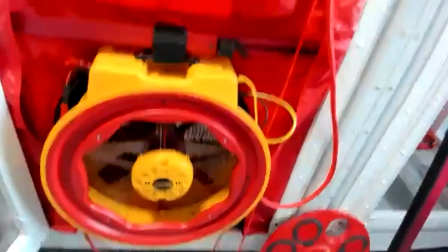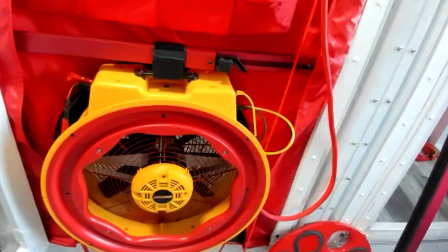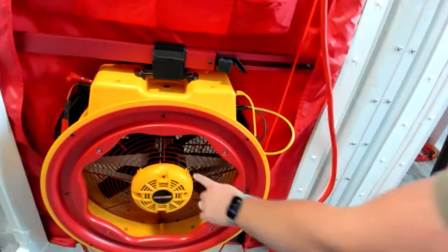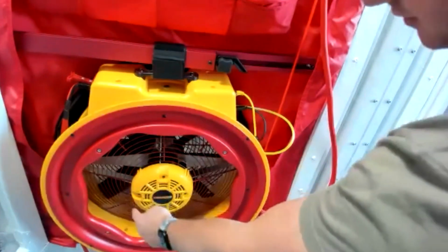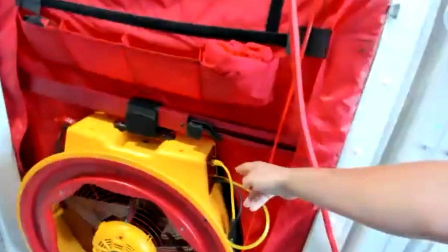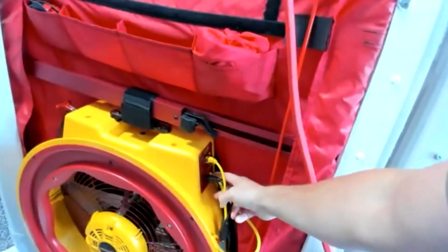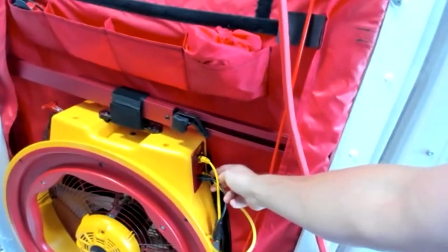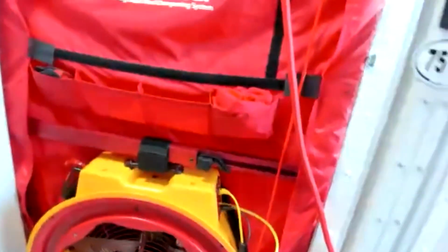When we're trying to determine flow, the way we record flow, as I told you earlier, is that we test houses to 50 pascals of pressure. That's CFM, cubic feet per minute, at 50 pascals. So that's our flow reading. Fan pressure is read at these 4 taps and averaged together, and then the manometer reads it here on the side where this yellow tube plugs in.